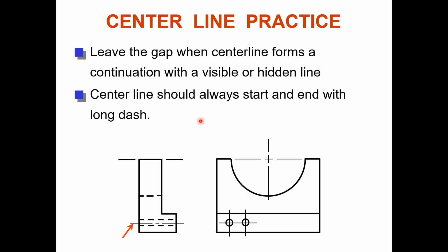Center line should always start and end with a long dash. At the ends it should end with a long dash. At the center you can use a short dash.